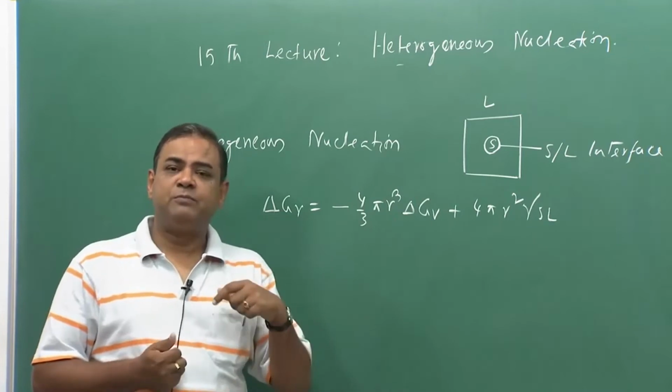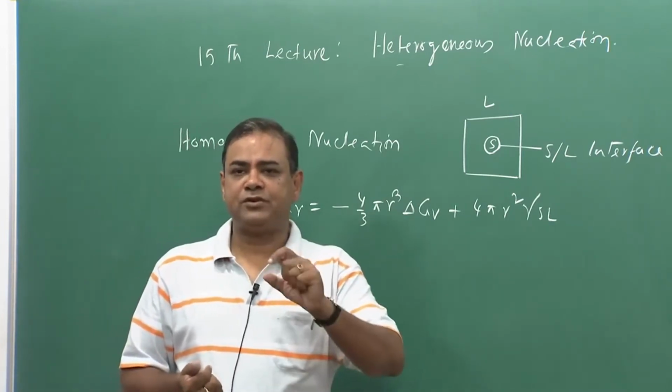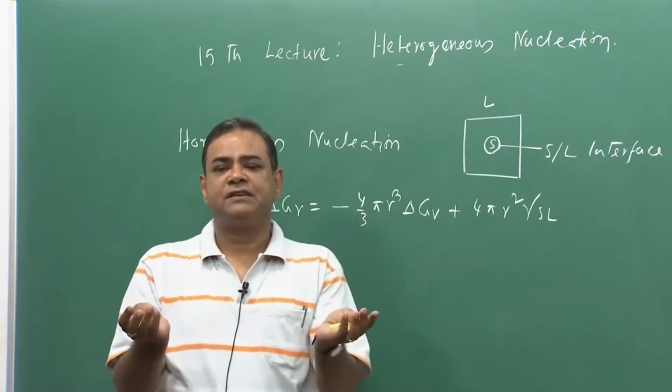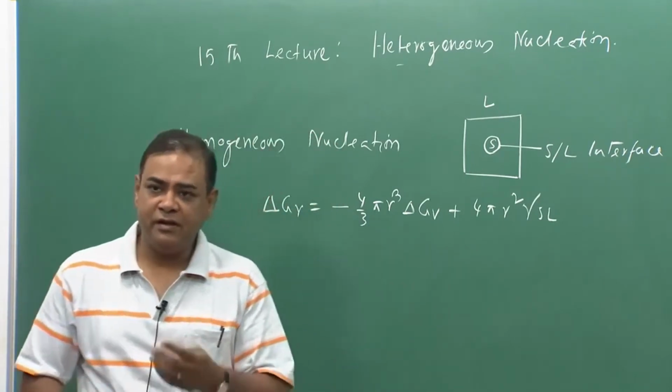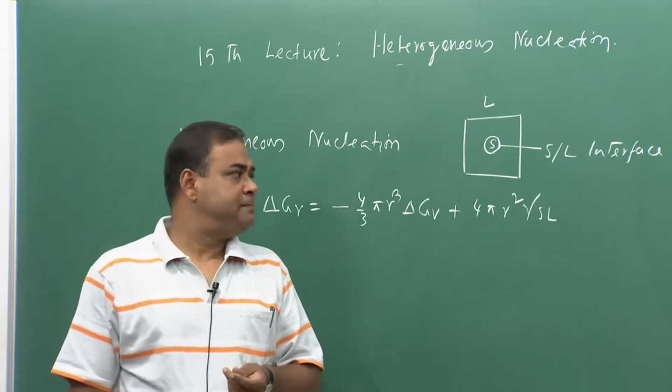So, if we do not have any mold surface assistance, the solidification mode would be a homogeneous mode, and people do levitation study. So, the liquid metal droplet is created and the droplet does not have any mold surface, it is a containerless solidification. There we do experience homogeneous nucleation.